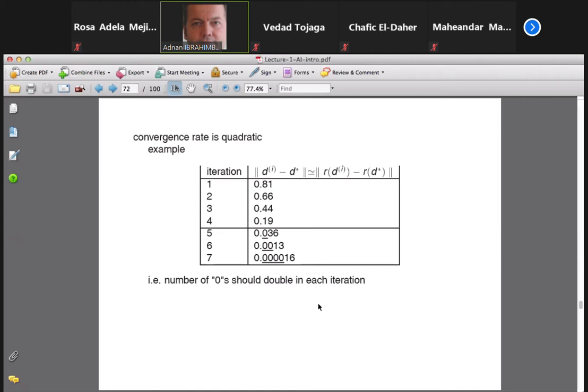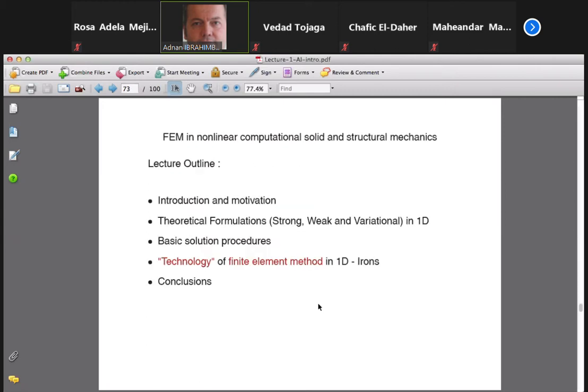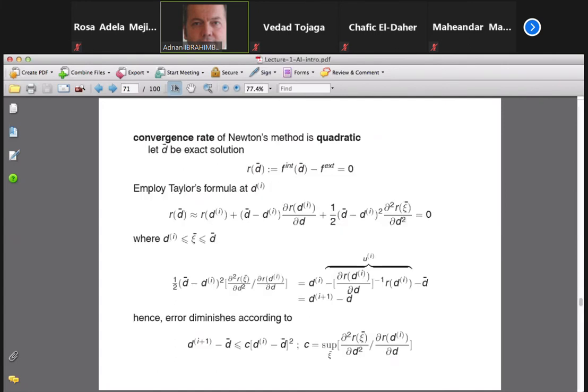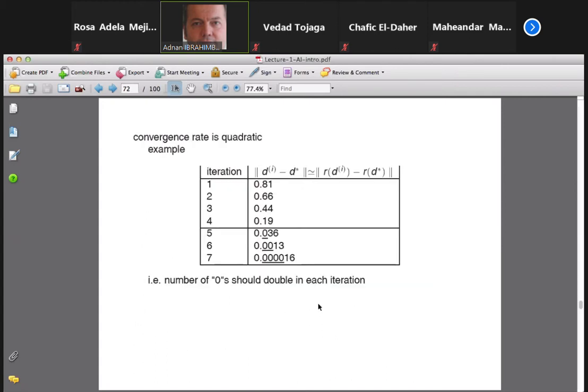And so basically, if you really want to have an acceptable solution, there's no reason to stop with only a few iterations. You basically can have a number of iterations as large as you want, and really drive down the residual to very, very small values as you go along. So this is really the solution procedure for the linear and nonlinear analysis. I explained to you Gauss method, and I explained to you the incremental method with Newton improvement.